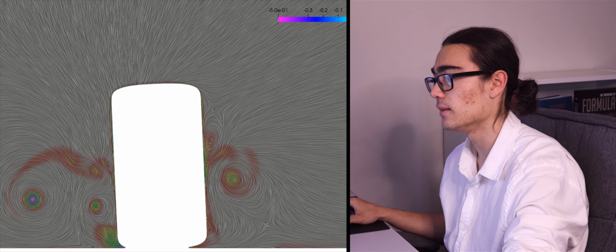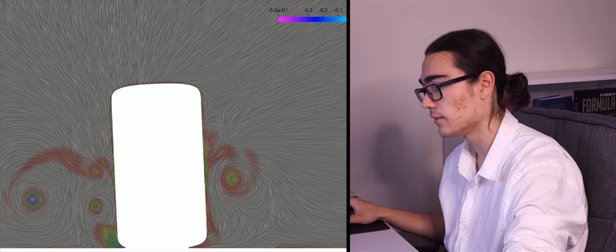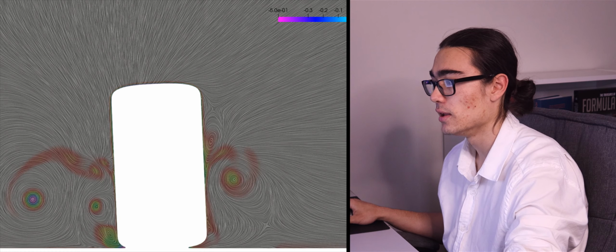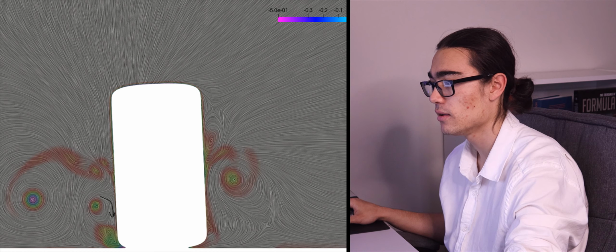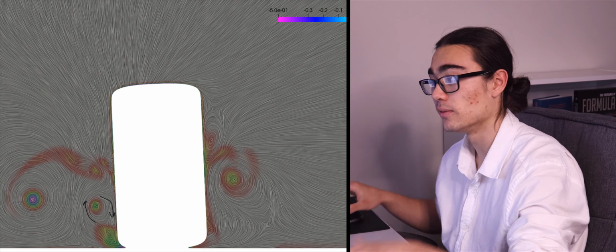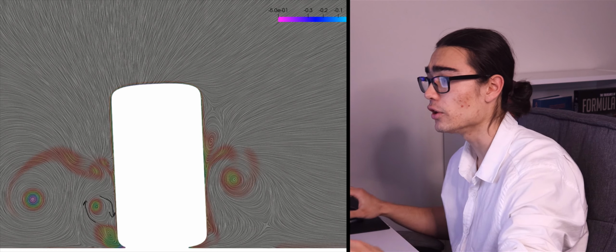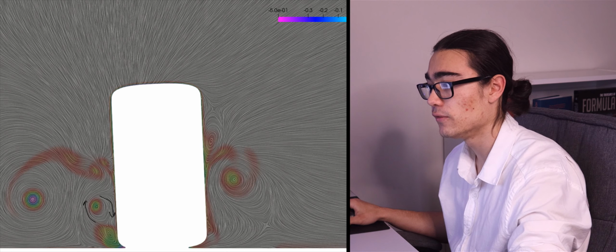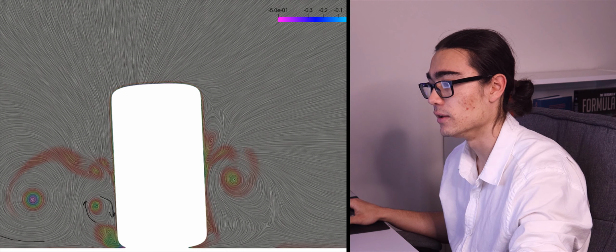And you can begin to see its influence on the squirt. So it's providing quite a large downwashing component here, and it's providing an upwashing component here, which is why the squirt was moving around the way it was. You can also see how big the flow field is that the Y250 is creating. And that's why we get a little bit of lateral support out of the Y250.